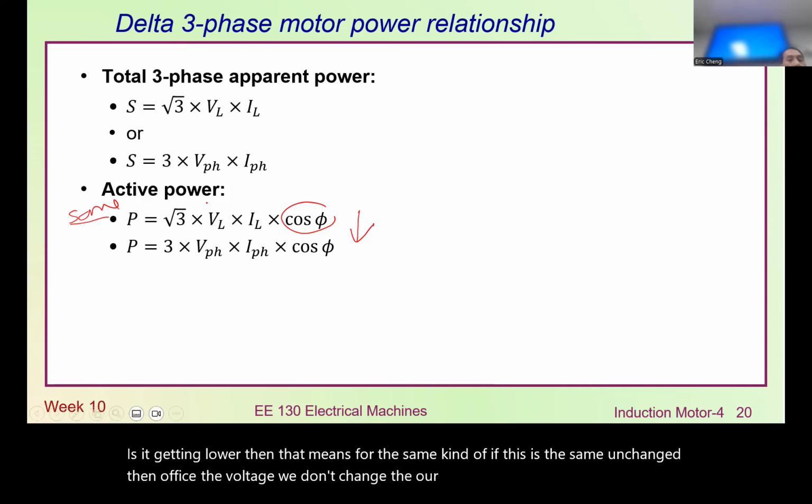In the question, because of the DC R1 resistance, we can just use an ohmmeter to measure exactly the resistance, quite straightforward. We don't need to use any power testing. Usually we use an ohmmeter, a multimeter, to measure the winding, just put it there to measure the winding. So 1.2 ohm, so that's why we can actually measure the power loss due to the DC part of R1 resistance.